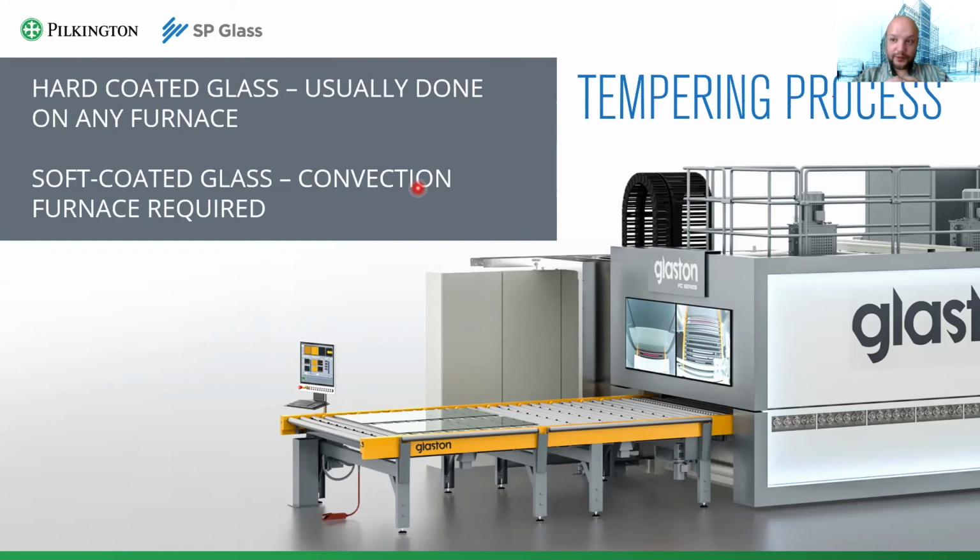At least some kind of top convection is a necessary requirement. But in my experience, most of the modern glass processing companies already have a convection furnace, whether they be top convection or full convection ones. And no, that's not an advertisement of Glasstone in any way, there are plenty of other types. As long as you have a proper furnace, you shouldn't be having any problems tempering soft-coated glass.